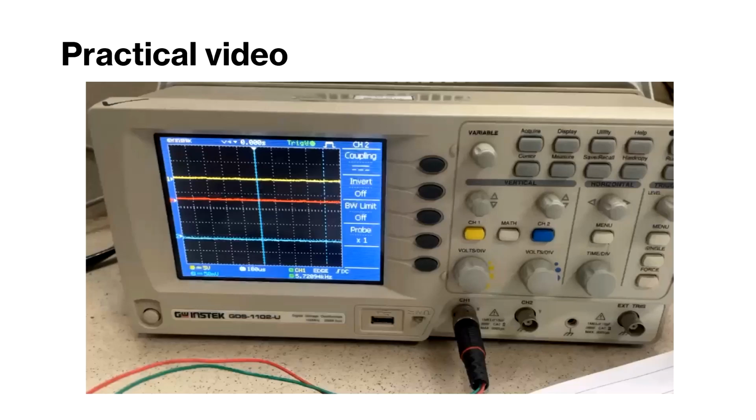Here comes demodulated output. Now what we do is we multiply the modulated output with a carrier signal having frequency same as that of the input signal. And after performing some calculations and passing the signal through a low pass filter, we get a linear relationship between the demodulated output and the displacement, thus helping us to measure the displacement of the core, whether it is moving to the left or to the right, that is in the positive direction or in the negative direction.